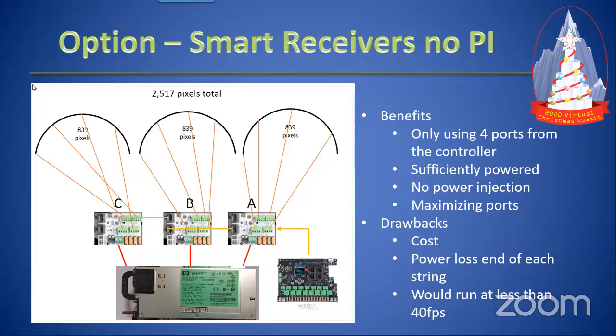So one more question. The F48 is powered by a 5-volt power supply, right? Correct. But I would still need a 12-volt power supply for these pixels. So I would just use a regular 12-volt Mean Well or whatever kind of power supply to power those. Correct. Okay.